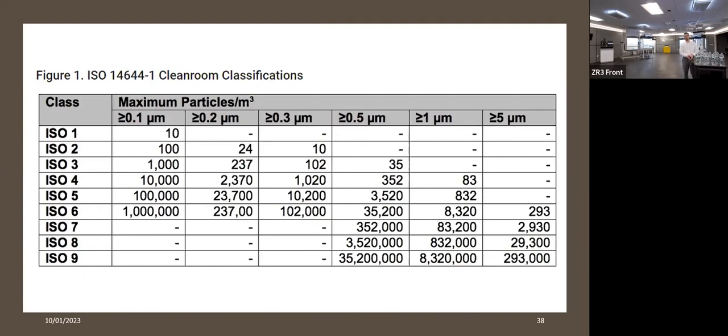But right now our systems go to about 0.3 micron. And it gives you the overall concentration that's actually present in that space. And you'll truly know how clean your air is. Because remember, the smaller the micron size, the greater the risk of going deep into our lungs, going into the oxygen in our bloodstream. So we want to clean that air.